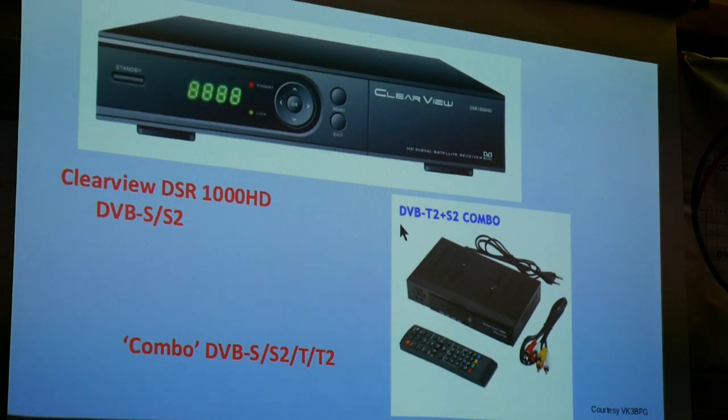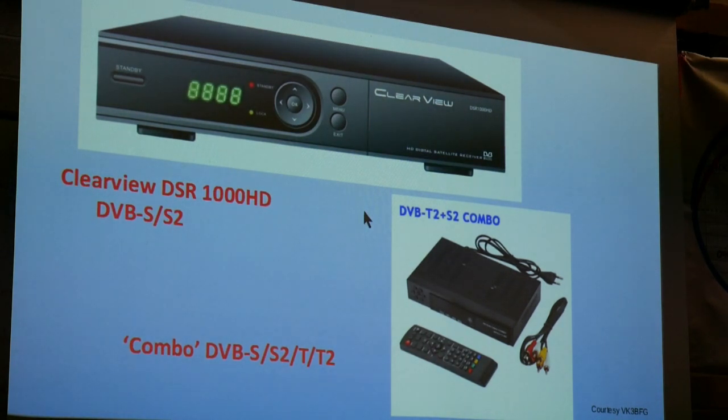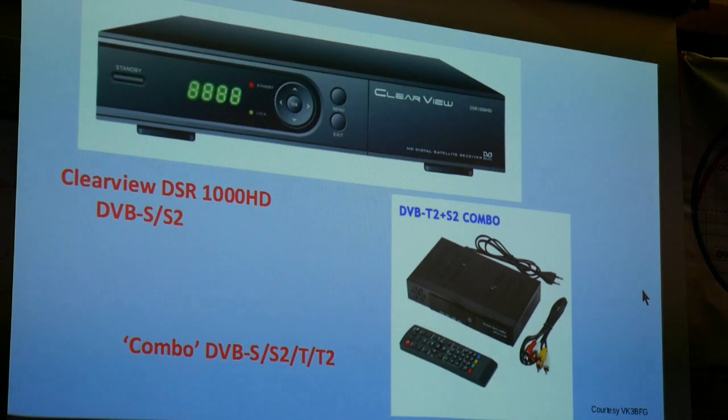But they messed around with the firmware after that, and after a while you bought these things and they wouldn't tune in anymore. So that was a bit of a shame. Of course, there's a way around it. You can always put a mixer oscillator on the front of it and just shift the frequency from 445 to one of the normal TV channels so this thing can pick it up. And you can do the same thing, of course, with your normal TV. So it's another way of doing it.